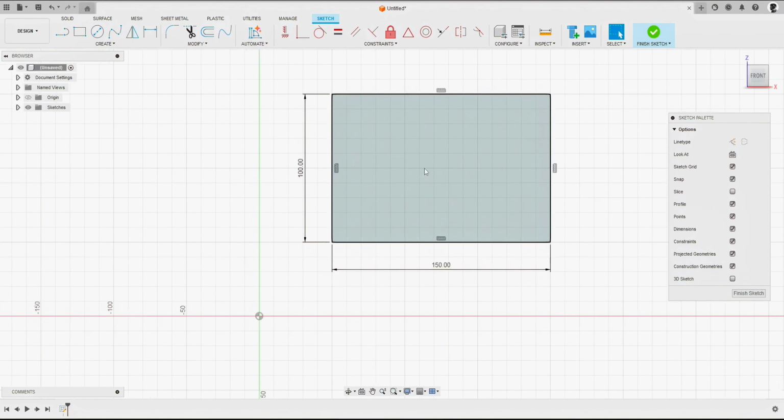Come over to this corner then. Go ahead and demonstrate a distance and angle chamfer. Now, one note when we're using this tool, where we want to define the distance, we need to select that line first. For example, if we want to control the distance on the horizontal here, we choose this line. On the vertical, we choose this line first. So let's go ahead and let's go with the distance on the horizontal. Then we're going to choose a second line, just the vertical, and start to see the chamfer form.